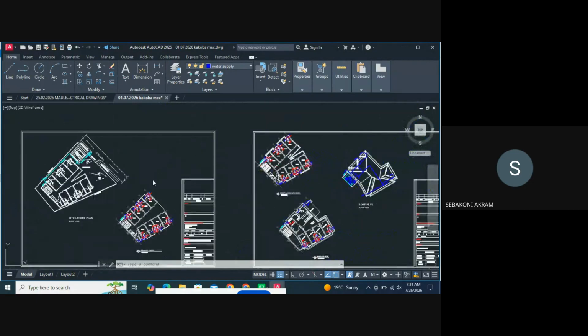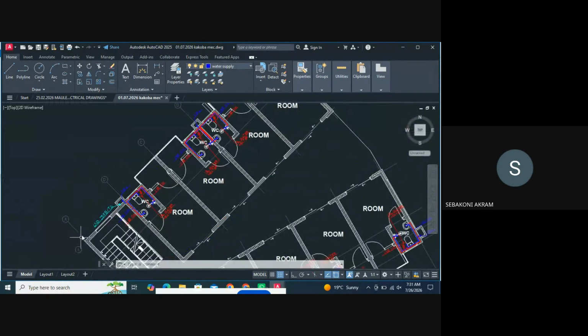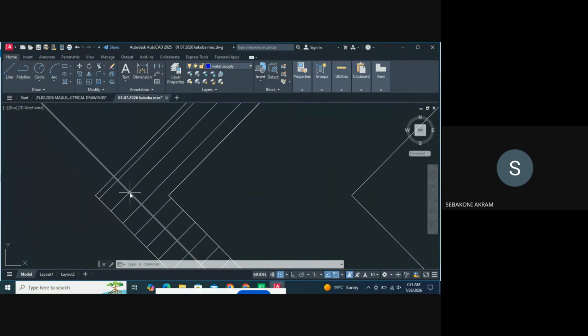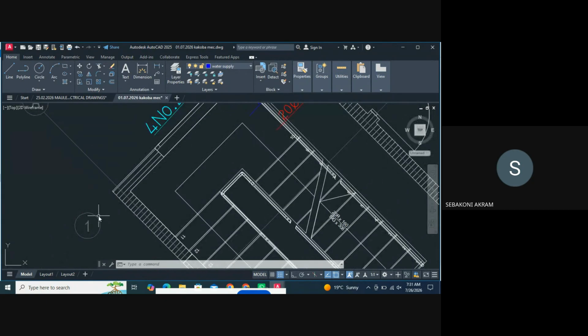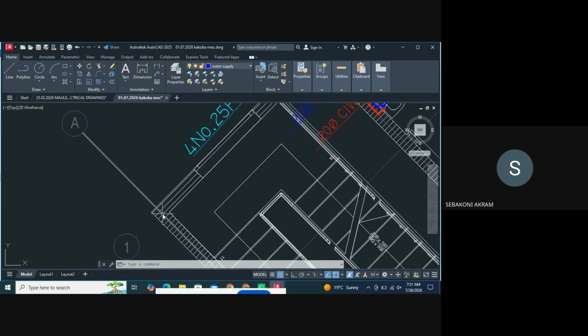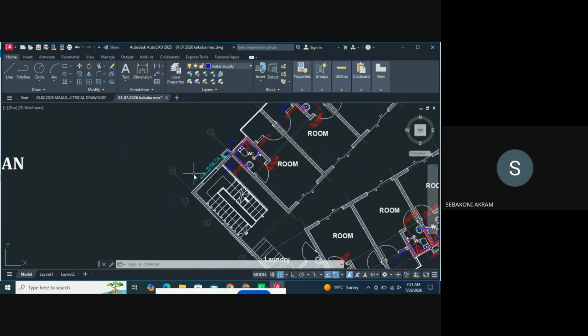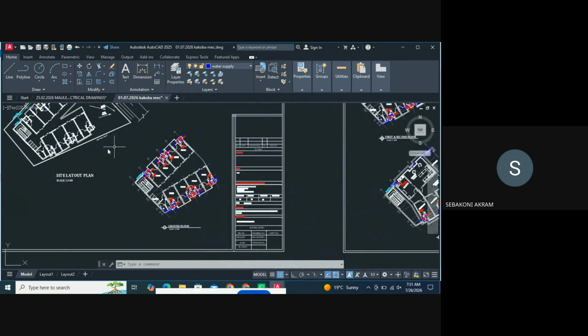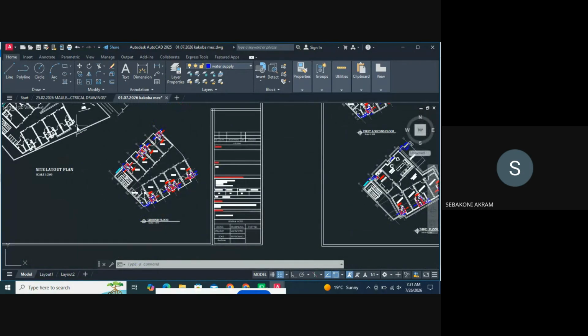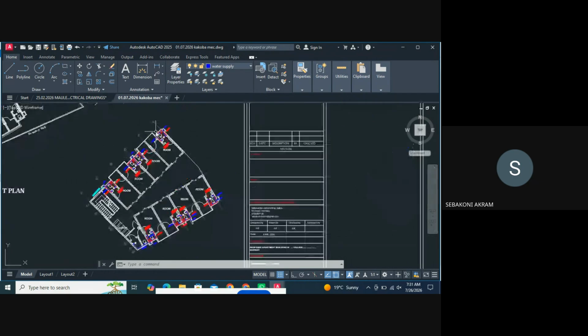But it is better when you have every drawing having grids. So you might take maybe an intersection between grid 1 and grid A. You take the intersection because you're going to find it on each one. It gives you the exact positioning. So that's how you move from the outer meter up to the top of the tanks.